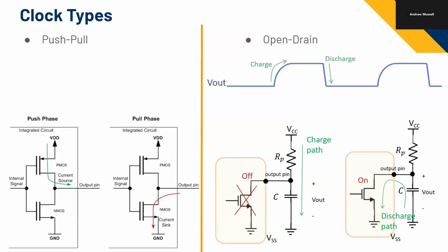In reality, you have voltages, which can be infinitesimally small, but with a digital to analog converter, you can only basically say this is 0 volts, or 0.1 volts, or 0.2 volts, or 0.3. If my signal was 0.25 volts, my digital domain would just say that's 0.2. So that's the main thing. The world is analog, so you always need to go back to analog.